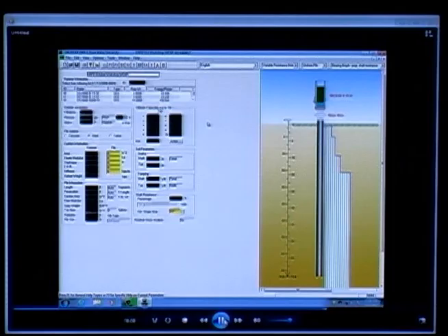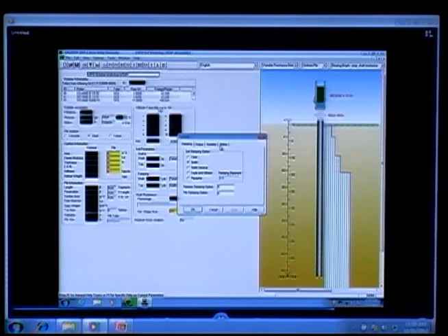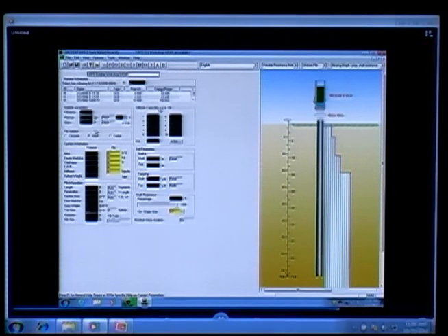Adjust the shaft resistance percentage from the drivability analysis. For this example, the percentage is 100. Select Option and click on General Options. Select the Stroke tab and Single Analysis with Fixed Stroke and Pressure. Press OK and return to the main input form. Change the hammer stroke to 7 feet.